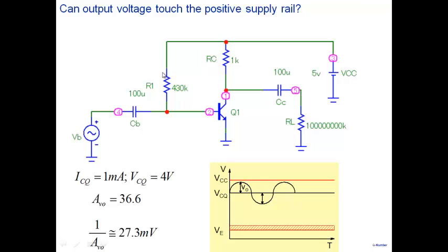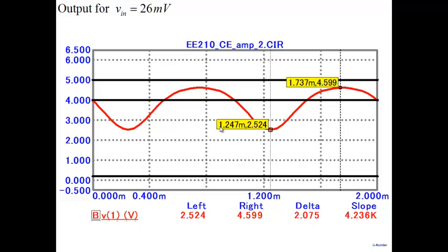We never thought about distortion, that my transistor is actually nonlinear. And this is what is happening because of the nonlinearity here. I'm getting a swing of 0.6 here and 1.5 here. In fact, I'm not able to reach 5 volt here. I could only reach 4.6.